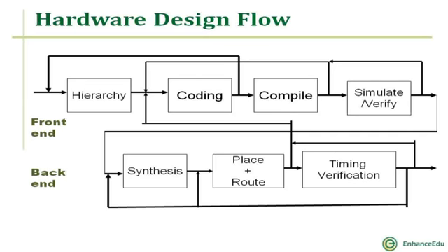And finally the compiled output is simulated or verified and then sent to the tool for placement and routing, and once the placement and routing are done, the timing verification has to be done once again to check whether there are any signal integrity problems or not. This becomes very critical, and many times a lot of money is wasted because of incorrectness in choosing the right component for the right problem.